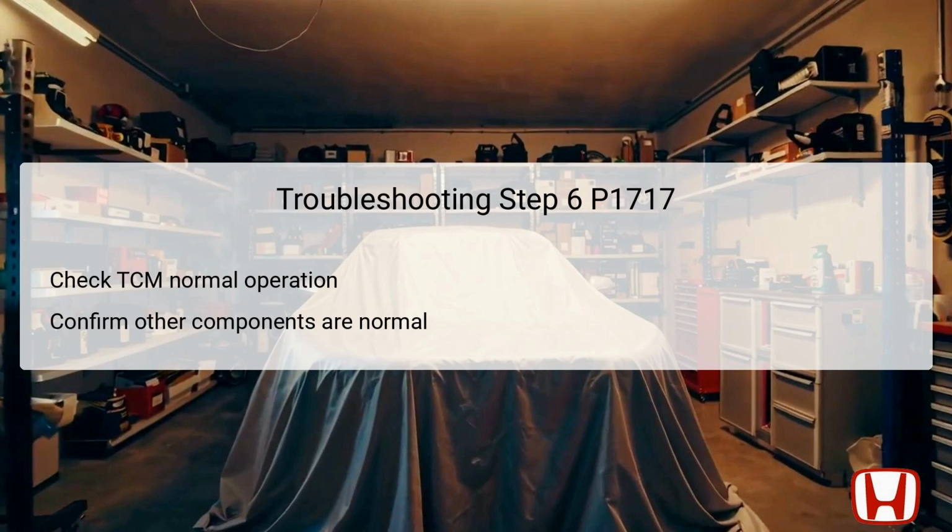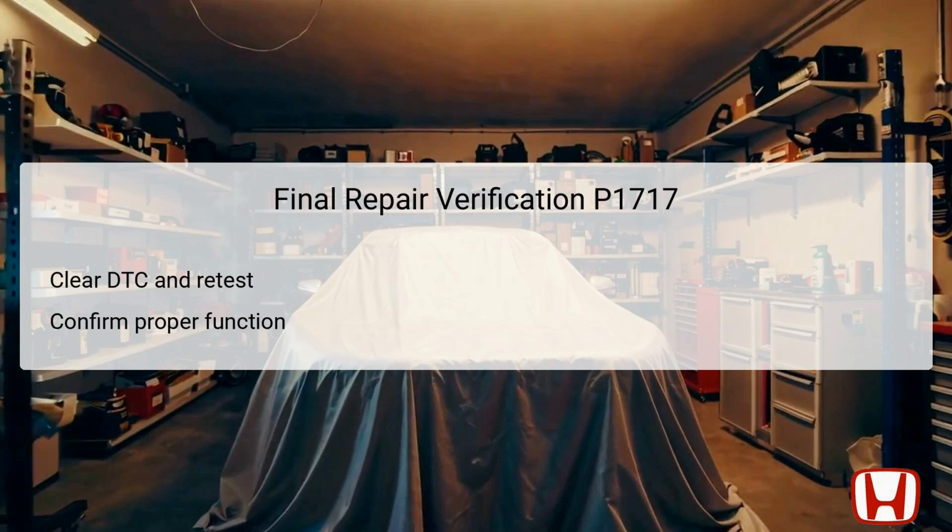Testing other related electronic inputs may also provide insight into the TCM's operational capacity. Any abnormalities found in this step may necessitate the replacement or reprogramming of the TCM to resolve the DTC. After completing all necessary repairs and corrections to the system, clear the DTC from the vehicle's computer using the HDS.